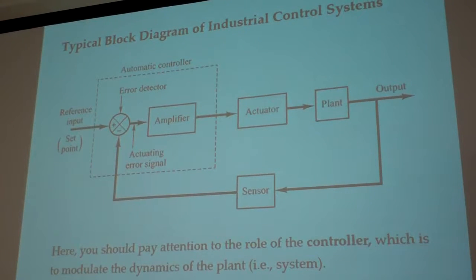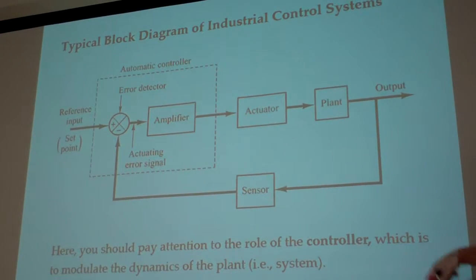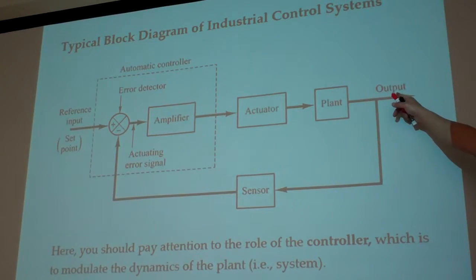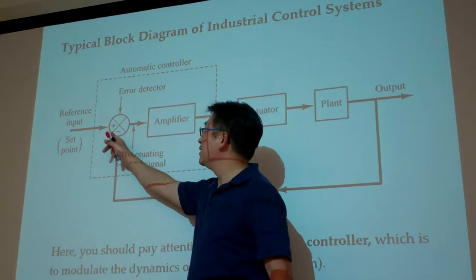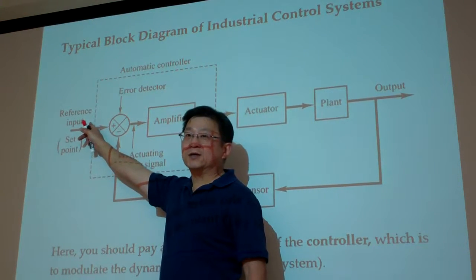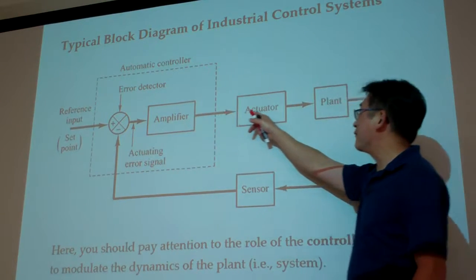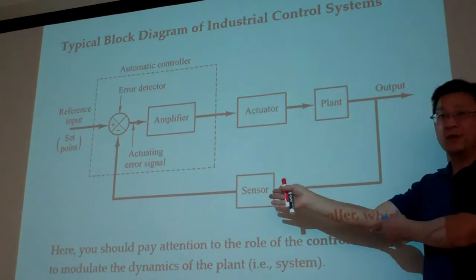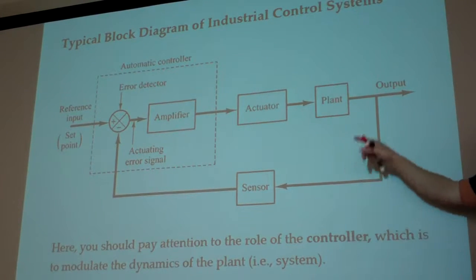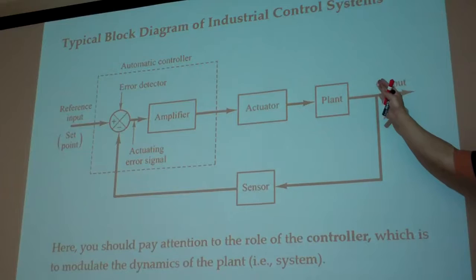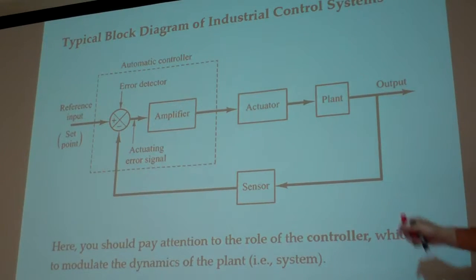In the next moment, say it powers up a little bit too much, say here is 91 degrees. The sensor senses, okay, here we have 91 degrees. Our design is 90, so here we have -1. So with -1, we ask the amplifier to reduce, stepping back a little bit, 1 degree. We keep moving, so eventually this will oscillate quickly and reach the desired value. So that is the thinking.